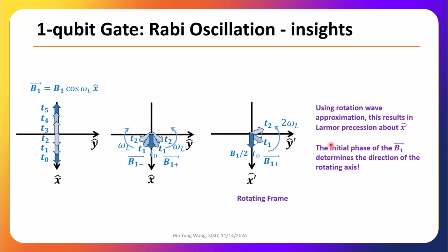But why is that? We can think a little bit more. On the left, I'm showing the top view of the magnetic field, right? So this is the sinusoidal field. You point very, very strong at the bottom, again weaker, and then pointing up and then strong. So this sinusoidal field is equivalent to two vectors rotating. This is rotating right, this is rotating left, right? For example, when the two magnetic fields are pointing in this direction, of course you get this strong one. Then when they are departing from each other, you get a weaker one, right?